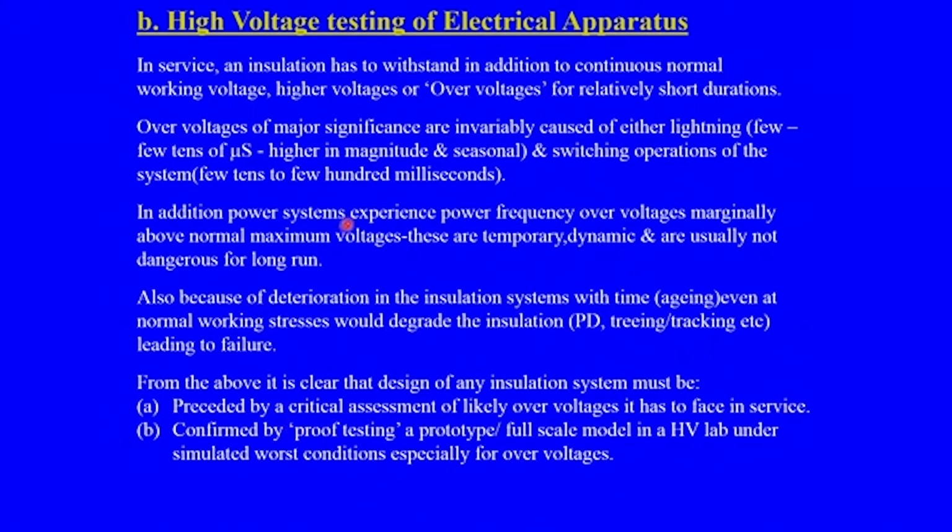So, from the above it is clear that the design of any insulation system must be preceded by a critical assessment of likely over voltages, could be lightning, switching, or related power frequency voltages, that it has to face in service.